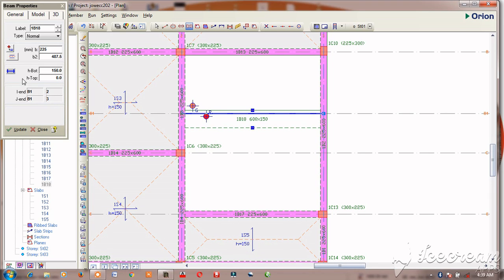So that's what it wants to get. It is an upstand beam now. Let me use 600 for it and check how it will be. So the center would be 112.5. Then come here and click update. So it has changed now.